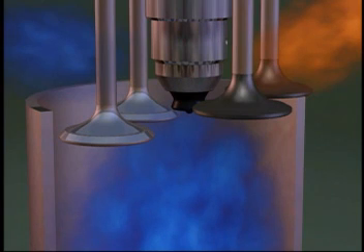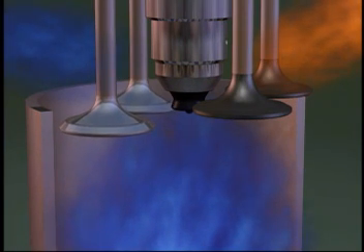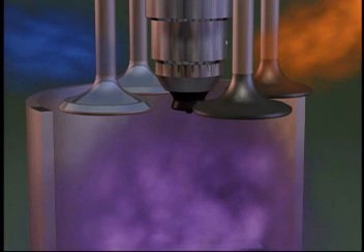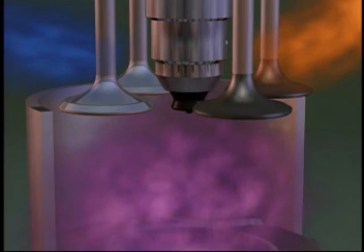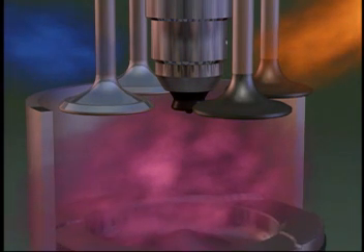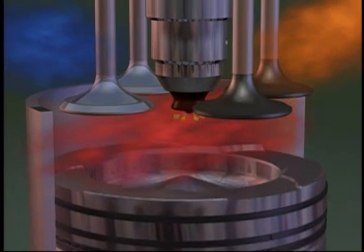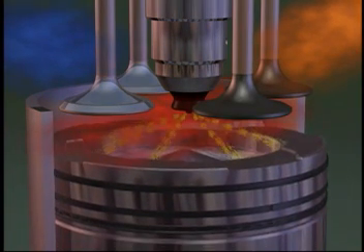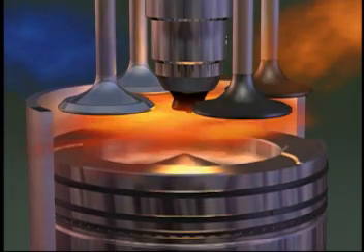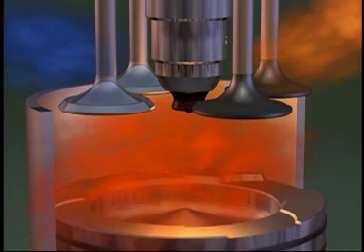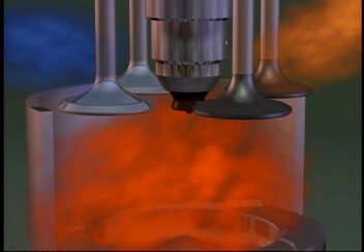In summary, for combustion to take place, the proper amount of air must be introduced into the combustion chamber. The piston on its upward stroke compresses the air, producing friction between the air molecules, which raises the temperature in the cylinder. At the proper moment, fuel is injected into the cylinder. Compression in the cylinder continues until ignition. At that point, combustion takes place, creating heat energy. A portion of the heat energy is converted to mechanical energy by driving the piston downward.